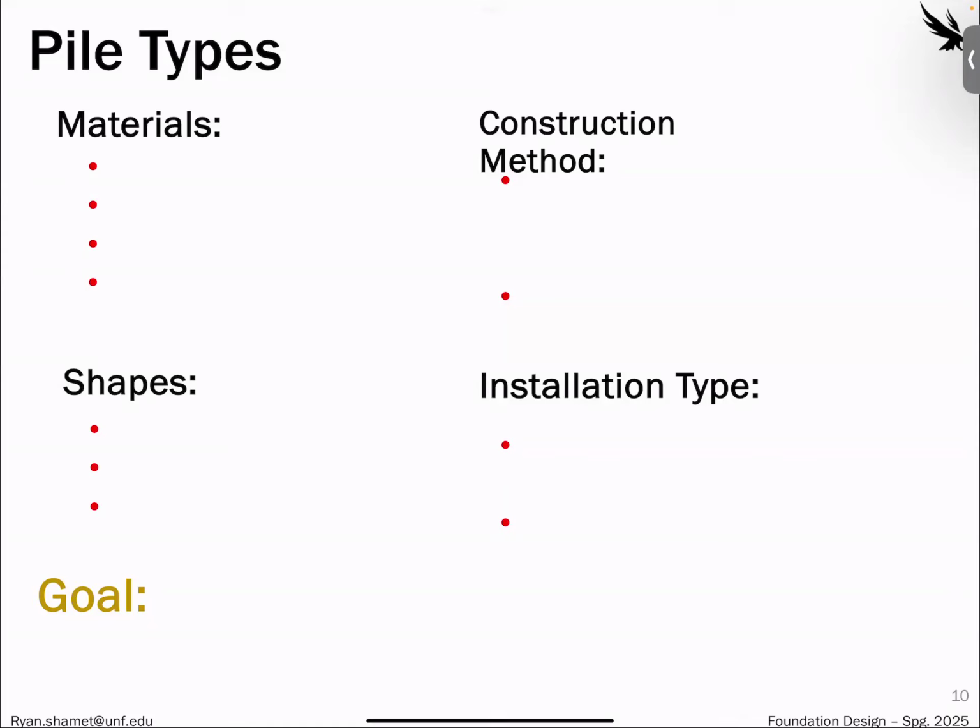So it's kind of fun when you're looking at some of these steel pipe piles that are spliced together, and we'll talk about the whole splicing thing, but you can get an estimate. Some of them for I-4 when they were under construction, you could see some of the piles extended and were spliced upwards of 280 feet. You'd be driving next to it, you'd see not 80, 300. That means there's 300 feet of pile underneath that point.